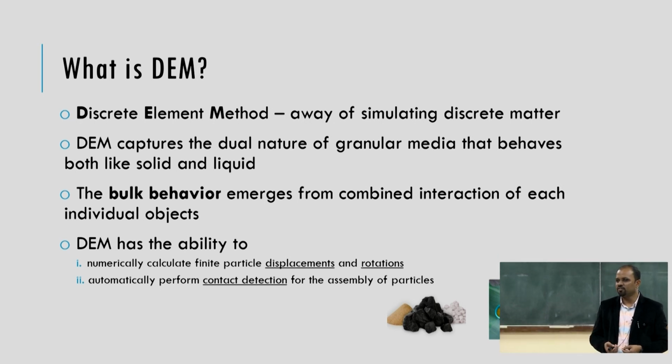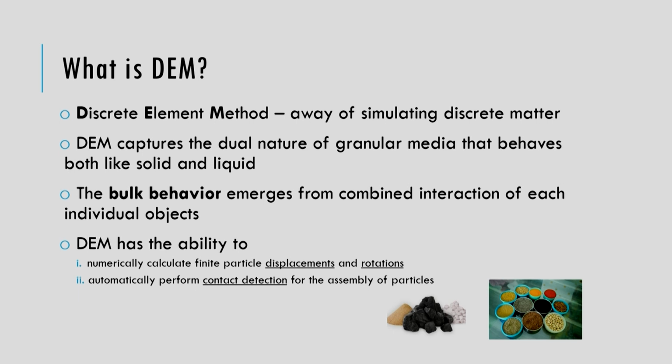What do you understand by coefficient of restitution? It tells the particle elasticity as well as the velocity behavior of the particle before and after collision. Yes, it is the relative velocity of the particles after the collision divided by the relative velocity before the collision. So it may represent the loss of kinetic energy in the motion. Its value is between 0 and 1: 1 is perfectly elastic and 0 is inelastic. So these are some of the properties which we take into account, and here we define the displacement and rotation like I told.